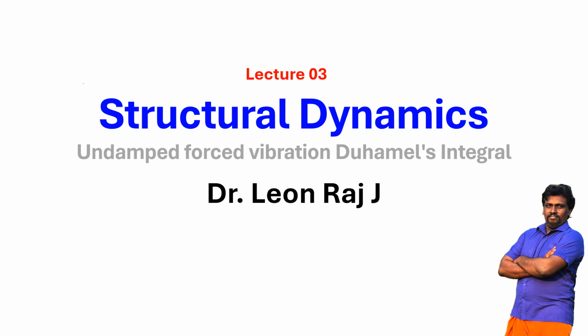Hi everyone. In this lecture, we are going to see the response of undamped forced vibration using Duhamel's integral. In lectures 1 and 2, we have seen responses of free and forced vibration, undamped and damped vibration. In this lecture, we are going to use Duhamel's integral to derive the response of the undamped forced vibration.